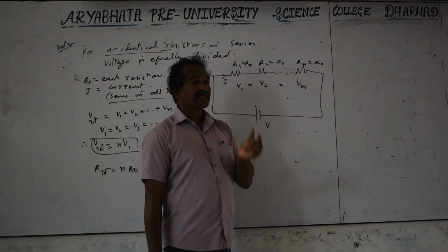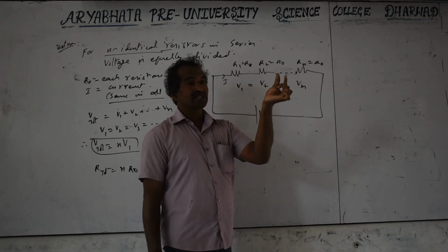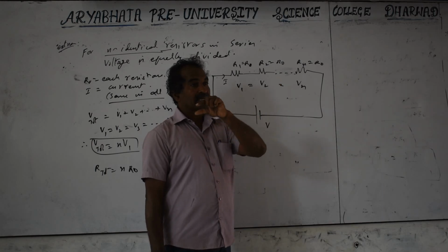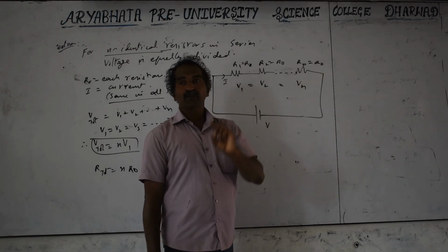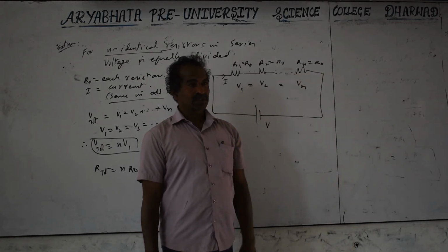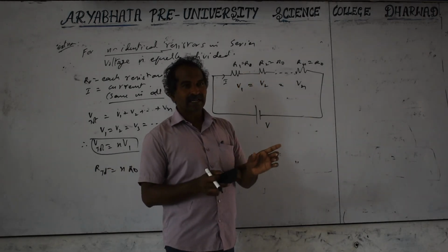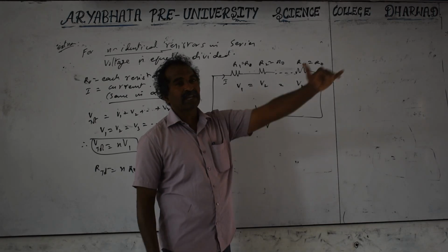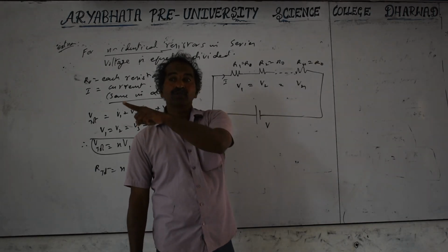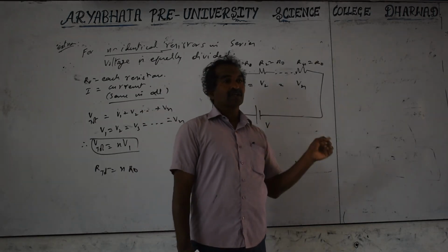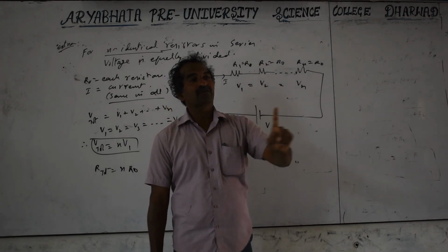In the olden days, they used to use small electrical bulbs near functions or temples, etc. They used to connect all the bulbs in series. Each bulb works with 2 volts to 6 volts. That means if connected directly to 230 volts in parallel, all will burn. So what you have to do is take 230 bulbs in series for 230 volts. The 230 volts is divided among all, and each one will get only 1 volt.